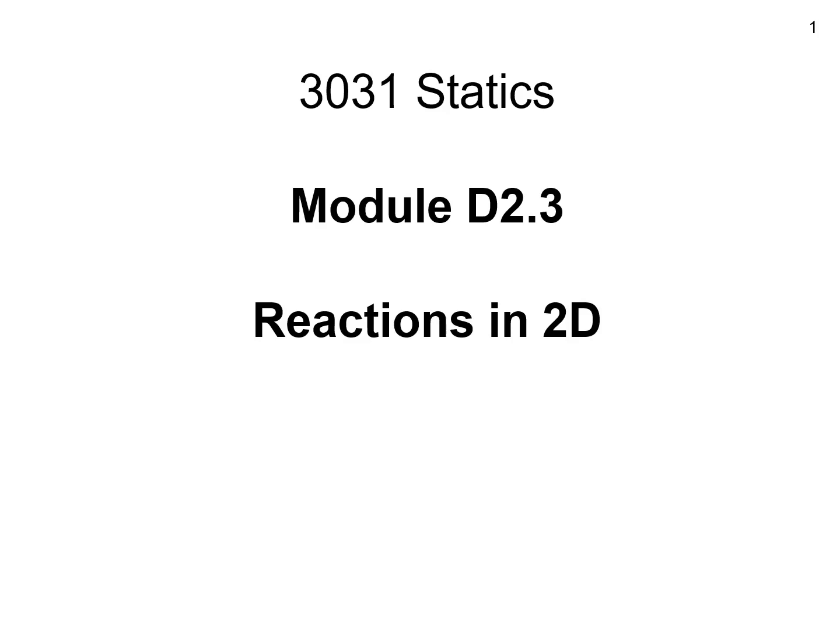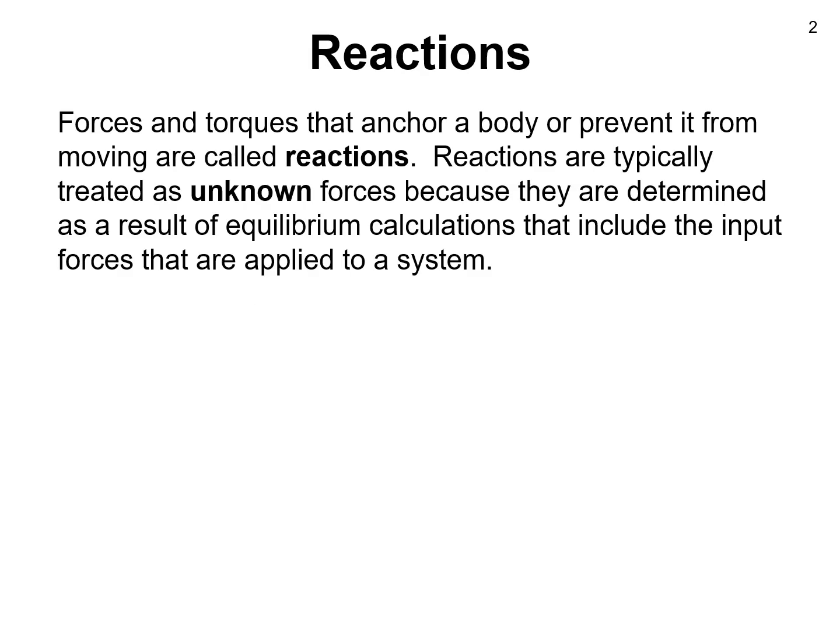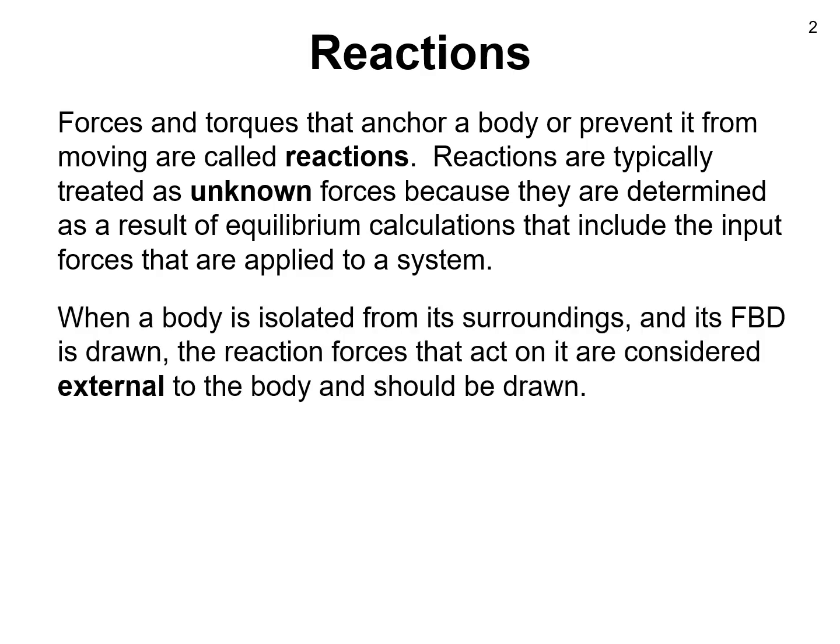In this module, we will discuss the idea of reactions in 2 dimensions. So what are reactions? Forces and torques that anchor a body or prevent it from moving are called reactions. Reactions are typically treated as unknown forces because they are determined as a result of equilibrium calculations that include the input forces that are applied to a system.